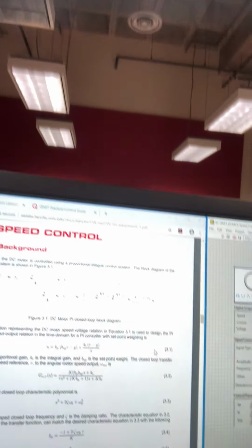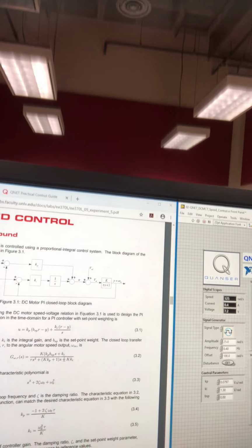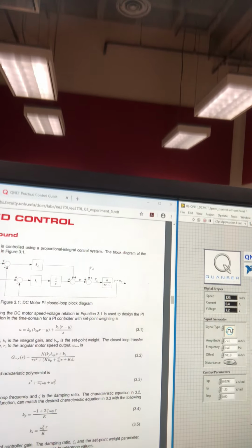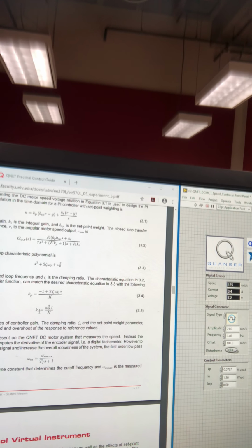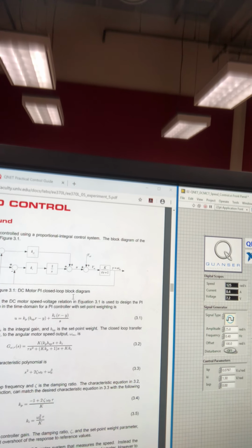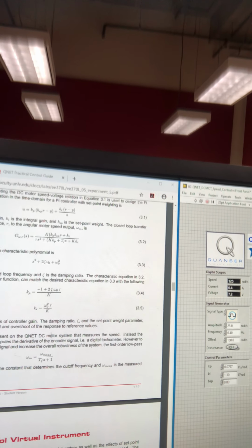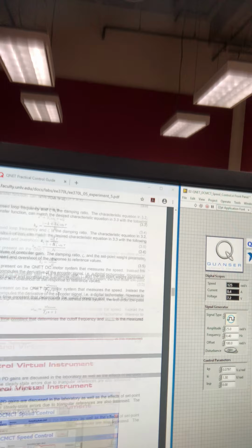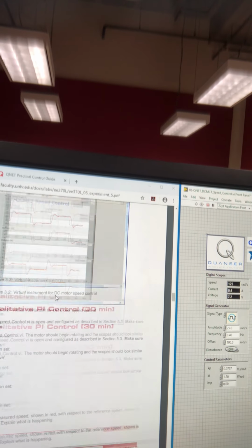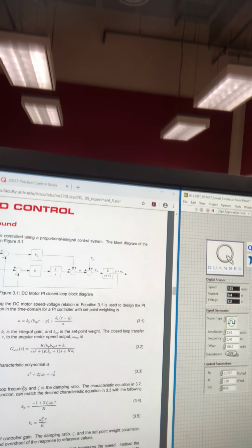Now we will use the K and tau we achieved from the previous lab to get the Kp and Ki we want to control the system. Also, we will need the Kc and omega 0 to calculate Kp and Ki.